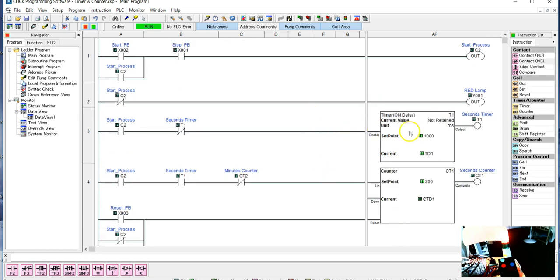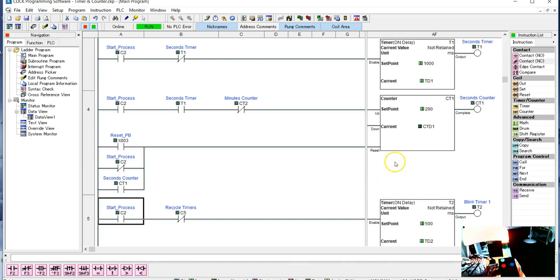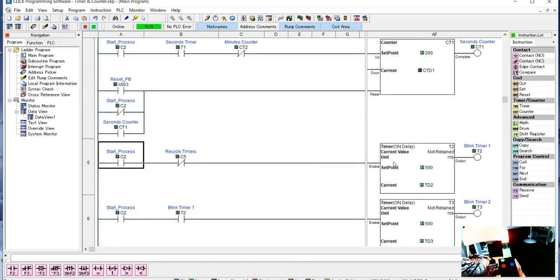So we're going to use some compare as we fill it up. And I think it potentially can fill up between 0 and 200, but really what we're going to try to do is drain it. Well, we'll fill it up. We'll drain it at 175, and then it'll drain down, down, down, and then we'll fill it up again when it gets to 25. So we'll use comparisons to set up when we're draining or filling.